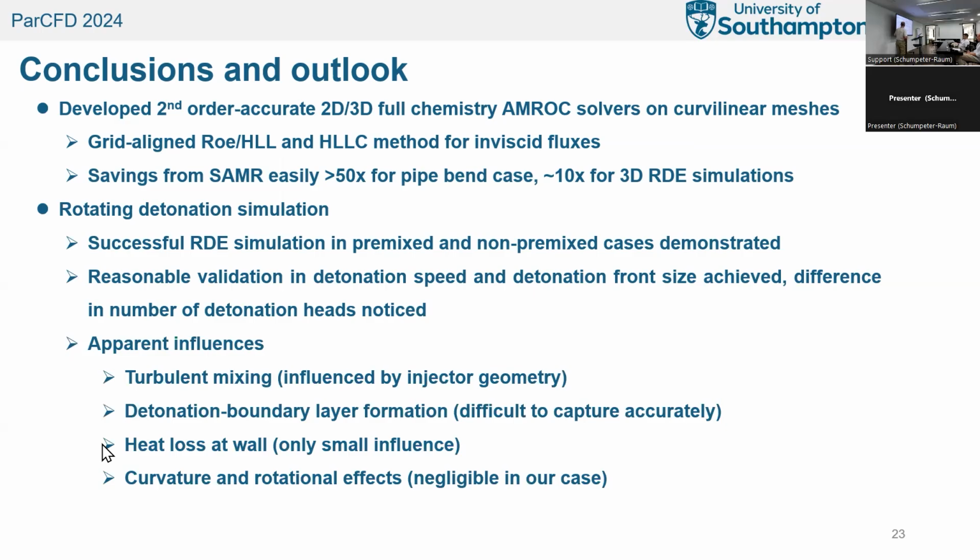It still is a challenge to do this properly, to match experiment and simulation for these configurations perfectly. The reason for that is more physical. The simulations are very ideal, while the experiments also have some significant flaws. The turbulent mixing, in my opinion the greatest influence on these configurations, is by far not as ideal in the experiments as you would hope. There is of course also detonation boundary layer interaction and viscous boundary layer, particularly if the engine is very small. So the loss from viscosity can possibly not be negligible, although nobody has really properly quantified this yet. Heat loss is very small.